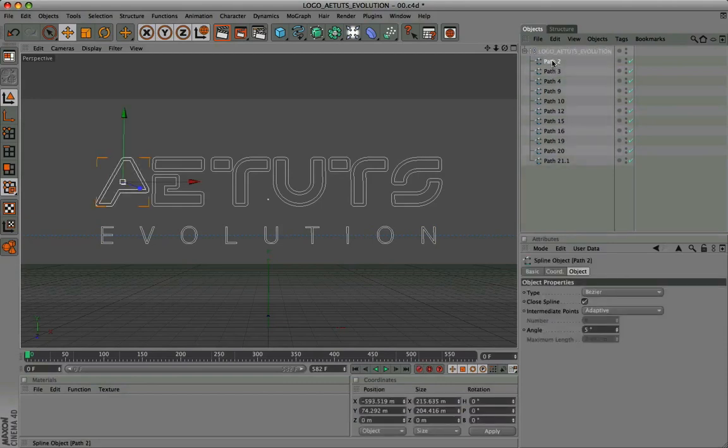One of the advantages of importing all the vector paths from an external program like Freehand or Adobe Illustrator is that every path reference does not lose its pivot axis. In this case, it is very useful, because during the modeling with the NURBS extrude tool, we have a reference to position the pivot correctly. Obviously, this will allow us, through the animation, to rotate and place each letter, or parts of the letters, in a direct and correct way.